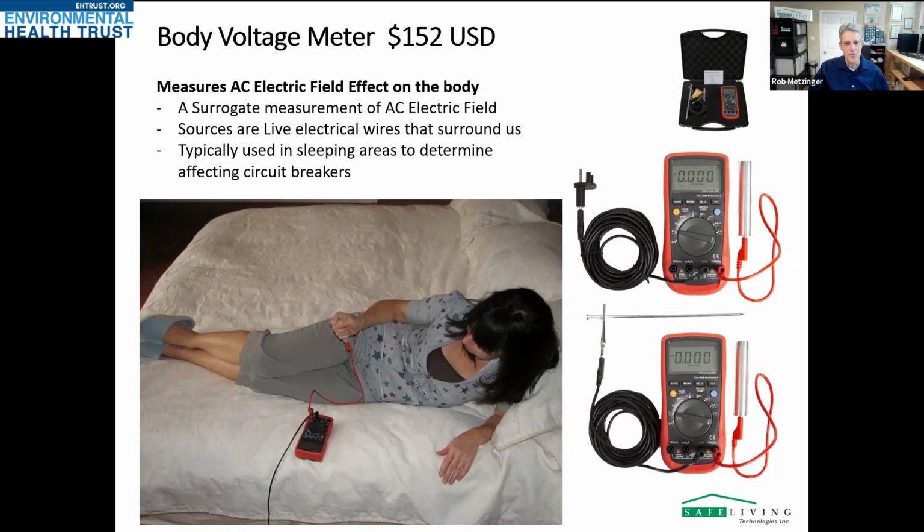Another important thing too is this meter kit comes with an outlet tester. So we definitely want to test the outlet before we plug this meter into ground. This will go into the electrical socket, but you want to test your socket to make sure the ground is valid and working beforehand. And then also this picture down below it, that's a picture of a ground rod sticking in the ground, basically. So that would be a ground peg that we use.